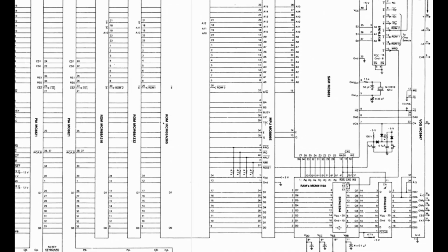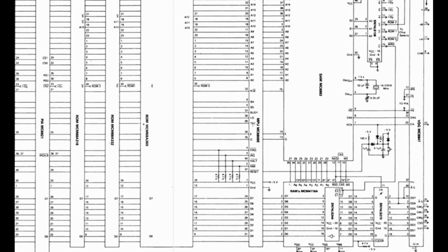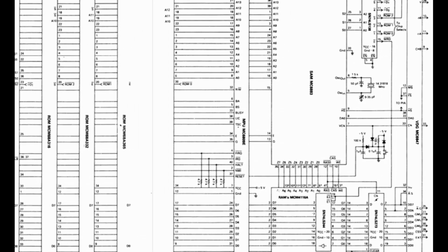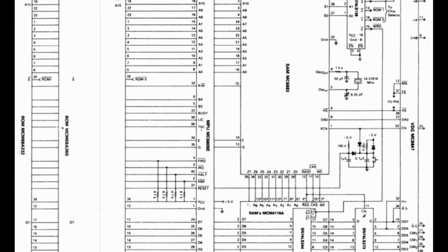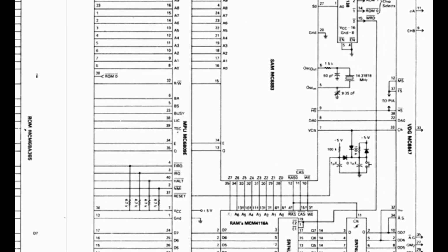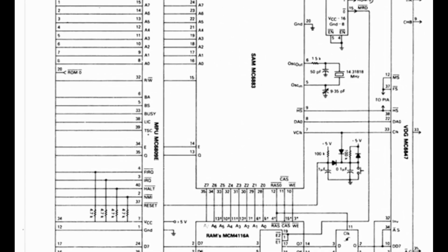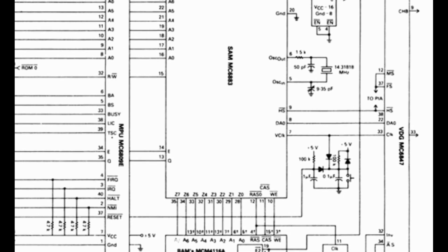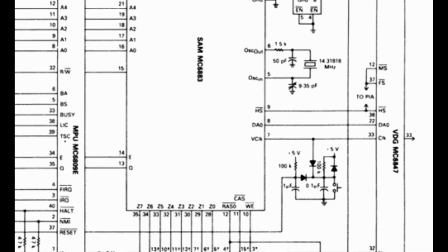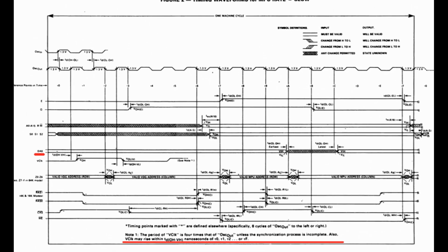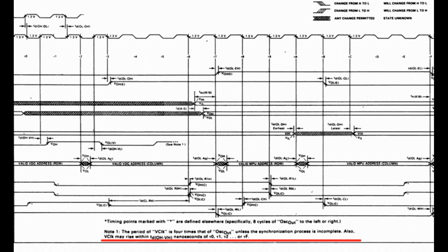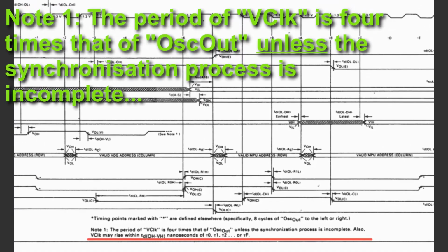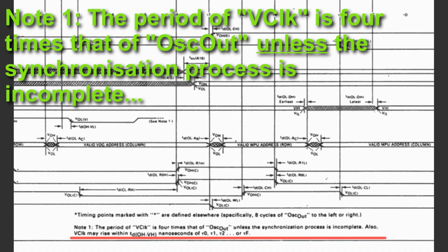That single address bit output. This connects to the SAM and drives the video address register, effectively an additional clock. The address bit, DA0, changes whenever the VDG needs a new byte of data. The SAM advances the video address and, in the video slice of the clock cycle, presents the new data to the VDG. Superficially, this is simple enough, but it comes with a nasty gotcha. DA0 can only change in a limited window within the master clock cycle. If it changes outside of that window, the SAM pulls the rug out and suspends the video clock until the change would be in phase.